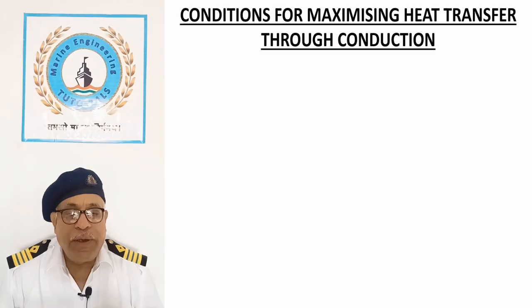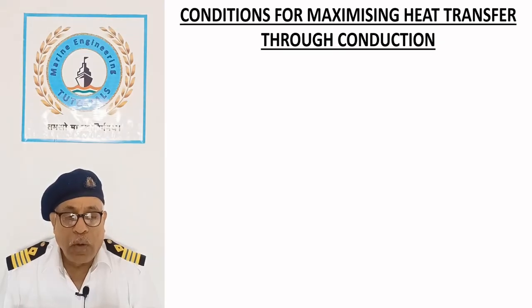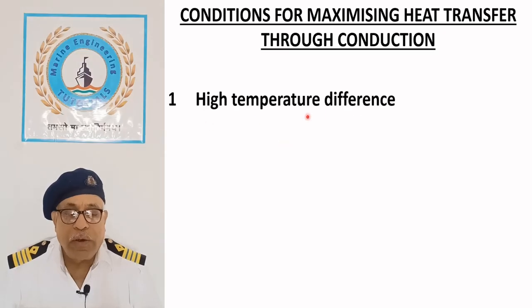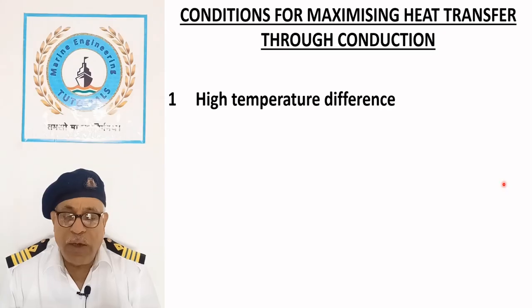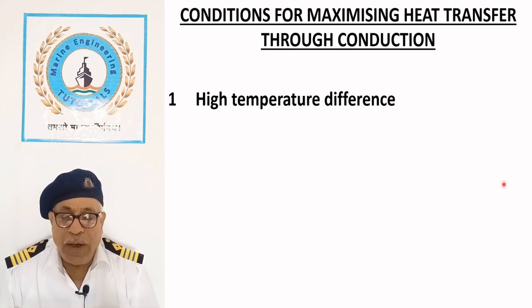Conditions for maximizing heat transfer through conduction. High temperature difference. We have learned that heat transfer is directly proportional to the temperature difference between the two fluids. This difference can be enhanced by adopting a counterflow arrangement where the fluids move in opposite directions to maximize temperature gradient across the heat exchanger.